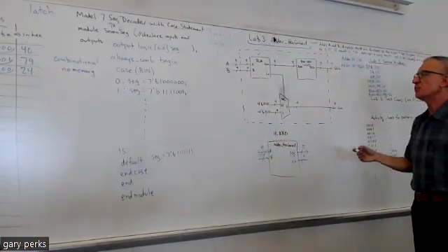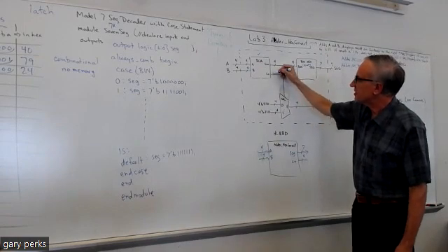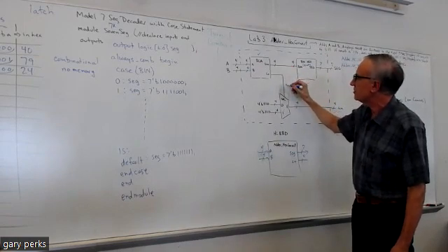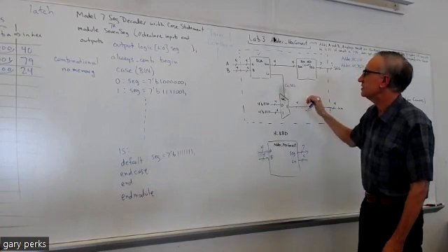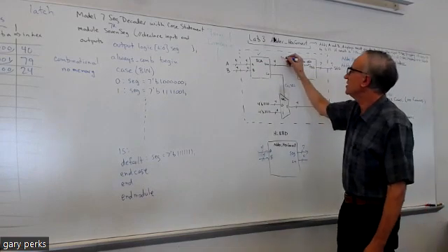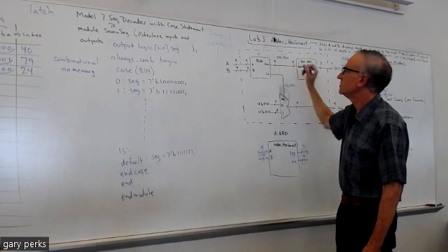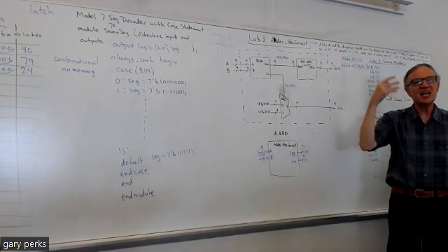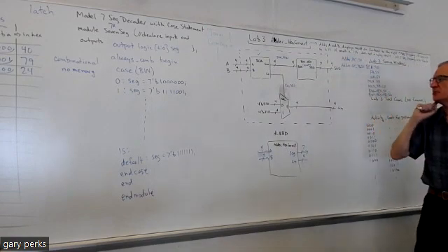In fact, I would try to be more descriptive. For example, the internal signal that connects this carry out to this select, maybe you could name it COSL or CO_SEL. And maybe this would be internal signal sum_bin. And again, if you get in the habit of being more descriptive with your names, it's going to help you, especially in CP233.